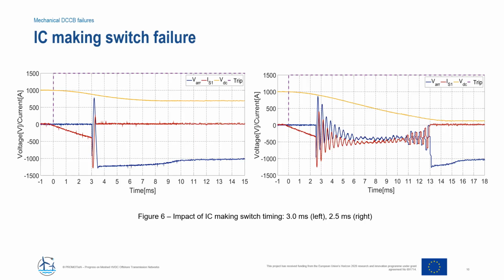Despite the fact that the vacuum interrupter current is slightly lower at this instance, the interrupter's contacts have not separated sufficiently to block the generated counter voltage. An arc is ignited and the consequences are clearly visible, with the current declining solely because the test circuit capacitors discharged at around 13 milliseconds.